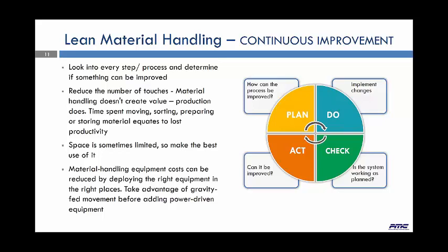Again, the rule of thumb is to always have a straight line flow from warehouse to assembly line. Can you minimize the number of turns, the distance, or congestion in those routes? So again, you don't want to have a lot of turns in your aisle, in your route, because anytime you're turning, you need to stop at those intersections, pause for a certain amount of time, and then make the turn. So you're wasting valuable time. Again, that's non-value-added time. So it all depends, again, keep an eye on all these things.